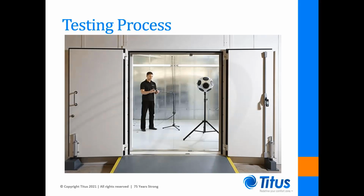The first thing we do when we're testing is to turn off all the equipment, close the chamber doors, and take a background sound level. This sets a baseline for the tests we'll be running that day. Although we know how to subtract background noise from our readings, the best practice is to only take readings that are at least 10 dB over the background level. We know that whenever 2 sounds are 10 dB apart, they're non-additive and the lesser sound will not be heard.